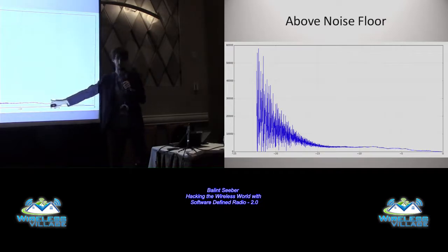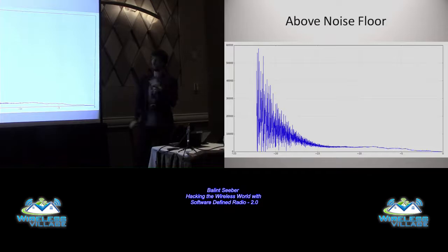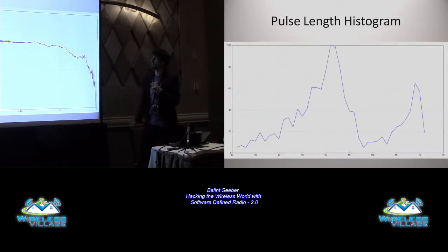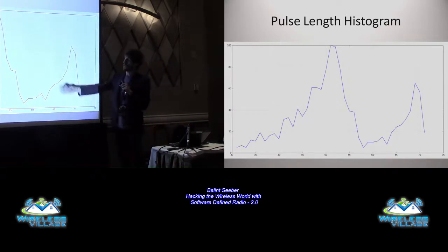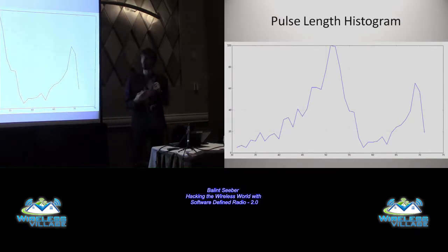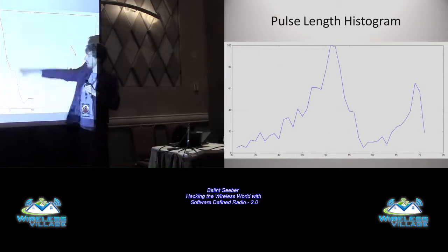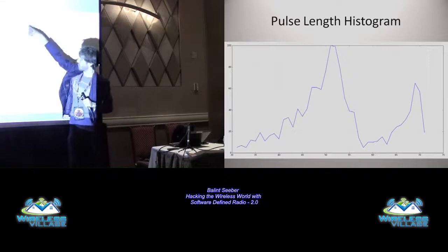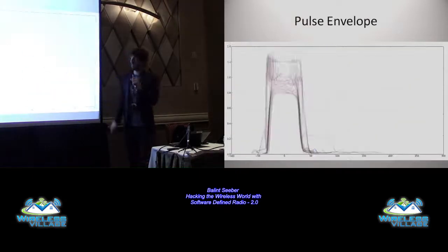So they're probably going to be few and far between, so again we're going to pick some high threshold here, and that's going to be our synchronization level. So you do the log scaling and you probably pick something around about there. Once you do that, then you can do a histogram of the length of these strong pulses. You can see there's quite a big peak there. So the chances are that our sort of standard pulse length is going to be whatever that peak maps to down the bottom, and you program that into the system as well.